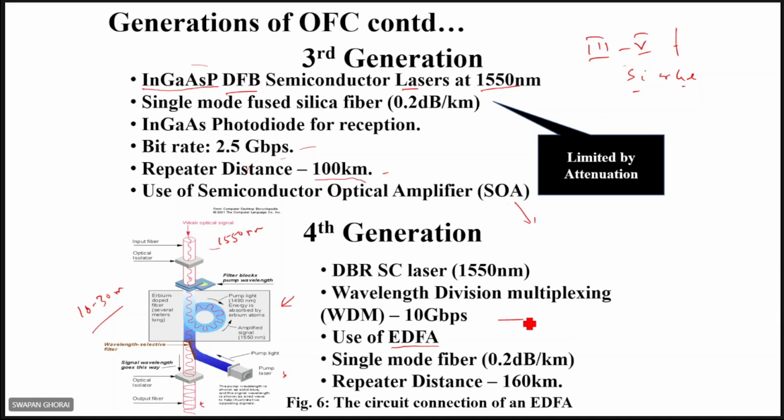An interesting feature of optical fiber is that for any other communication, you need only one carrier. But here, multiple carriers can be used in optical fiber, since it's based on light signals, so there'll be no interference in this case, right? Because for interference, you need the waves to be coherent in nature, right? Should be coherent. Then only interference will be there. But if different lambdas are there, there'll be no such coherency. So there'll be no interference. So many wavelengths can be transmitted.